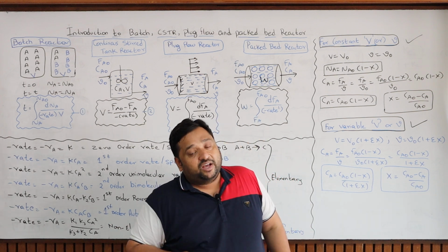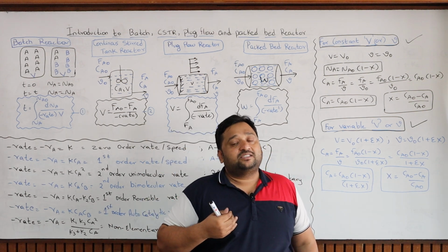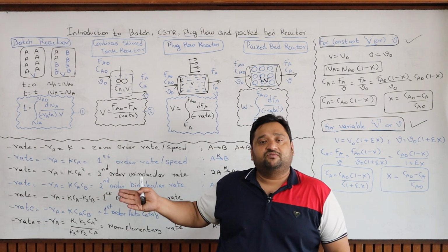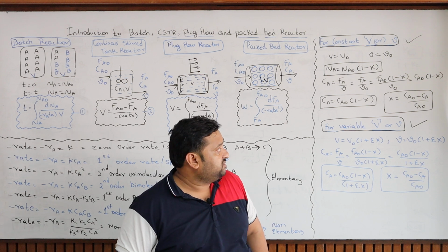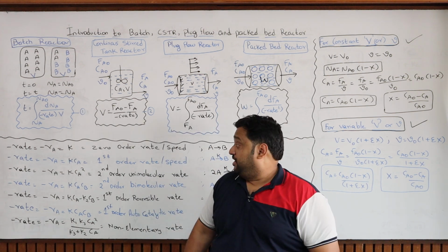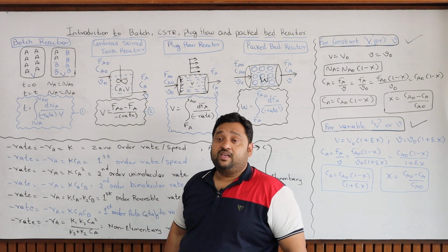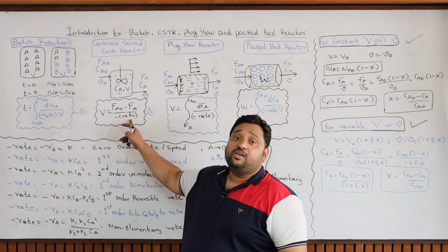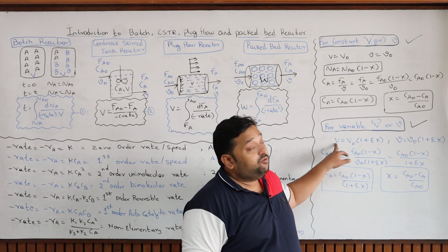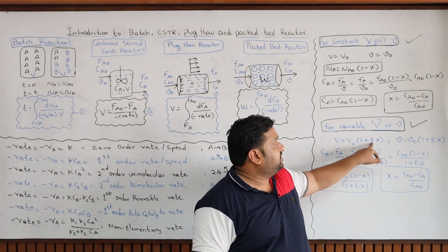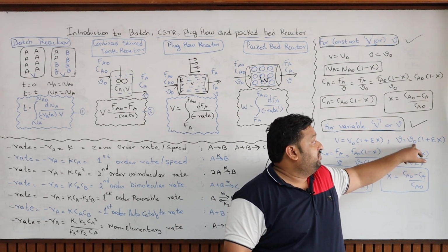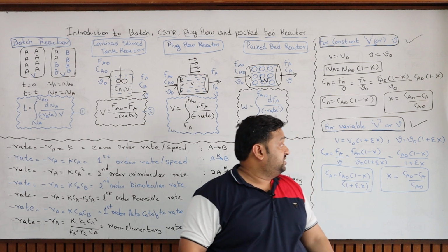So in such cases, you need to take into account the volume expansion or volumetric flow rate expansion. One way of handling this is to find the epsilon, because I have given a detailed explanation of epsilon in my stoichiometry lectures. Let us see what changes, because the agenda is to find CA, which finally I have to substitute here. Final volume is equal to initial volume into 1 plus epsilon X. Final volumetric flow rate is equal to initial volumetric flow rate into 1 plus epsilon X.